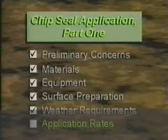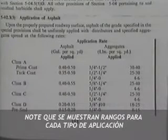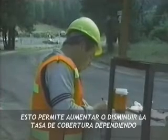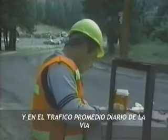Many agencies use a table like this, that lists the rates for both the liquid asphalt and the aggregate. Notice that a range is given for each rate. That allows you to increase or decrease the coverage depending on the condition of the surface and on the road's average daily traffic.